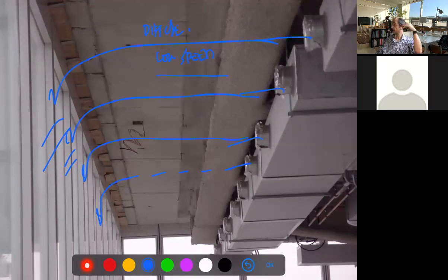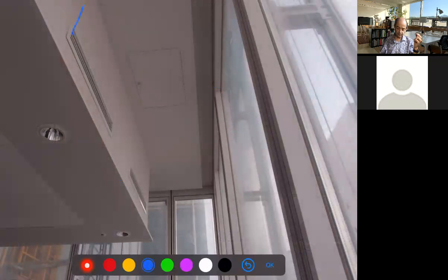So you don't feel almost the air moving, but you have a lot of volume, right? So it's large volume, but a low speed. So you have a very good regulation of the air without having discomfort. And this is how it looks when it's finished. So you have diffusers which actually take more than 50% of the area, and there is starting there and disconnected in the other side of the floor.